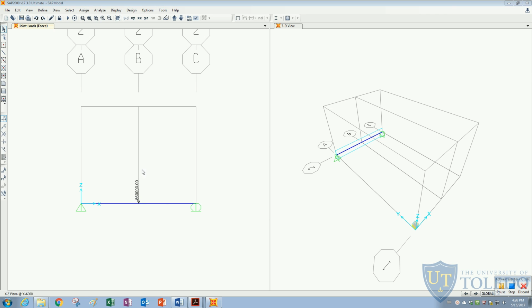For the type of loading that we are going to use, just to exemplify in this video, I'm going to do both a force-based analysis and a displacement-based analysis. In a force-based analysis, what we do is keep increasing the load on this beam until it cannot resist any more load and fails. In a displacement-based analysis, instead of the load, we apply the displacement on the beam and check how much force comes out from the displacement we imposed.